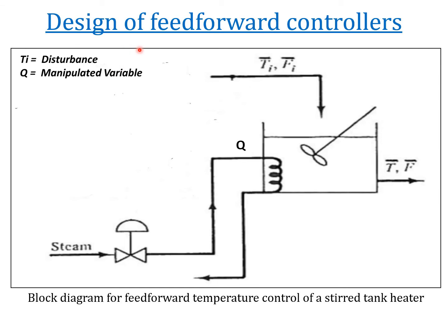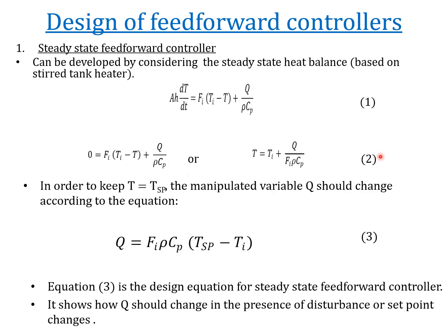Basically, let's see the design of a feedforward controller using this example. A tank heater, and these are the temperature input coming in, output coming out, and in this case we control the steam coming into the heater to manipulate the temperature output. Okay, so first of all, in designing, we develop what we call the steady state feedforward controller.